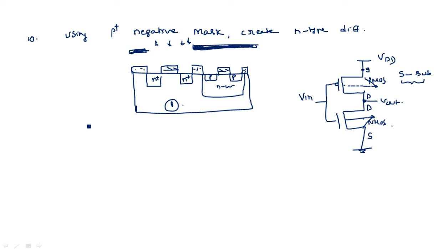That substrate terminal we have not shown anywhere, but when you are working with the tool, definitely the substrate terminal should be connected to the source. Substrate and source should be connected together here and here. Source and substrate should be connected together. So as the substrate of these terminals will not come outside, we should diffuse that substrate material also beside this N plus region.